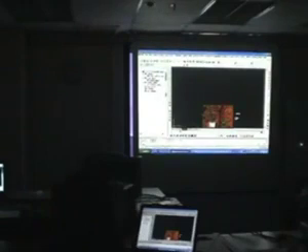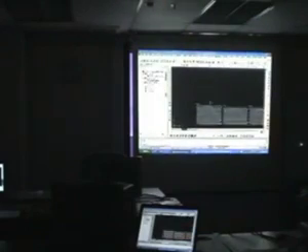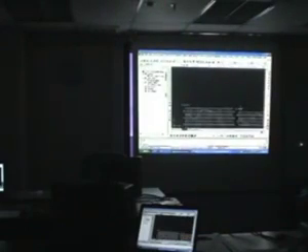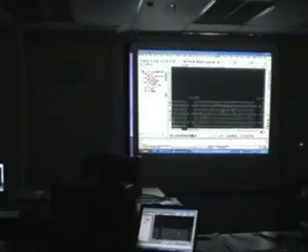The interval which I have set is dependent on the grid value which I put in during the site definition. In this case, I put 1. So if I zoom into the sections, you can see that each interval is 1 meter. Yeah, so it can go as small as you want, but of course these are 1 meter intervals between each other. At the moment, it's taken 1 meter from the border.